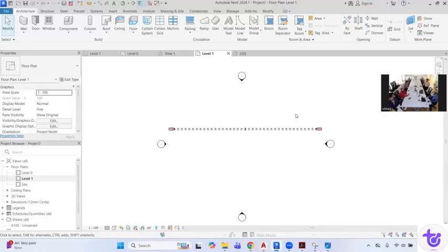Yes, with this subcategory, we can control anything. This is a very helpful option. These subcategory things are applicable for our families. We can use these in each and every family, anywhere. Yes, anywhere. In the object styles, you can go to any category and create a subcategory.